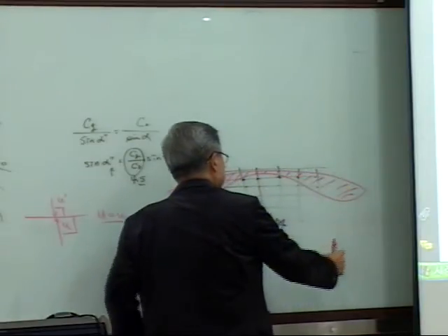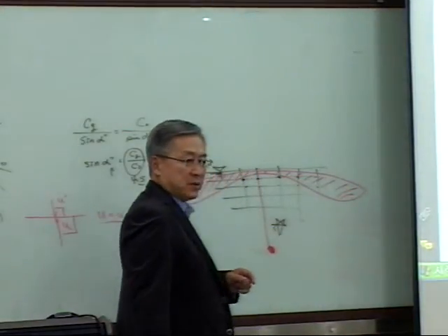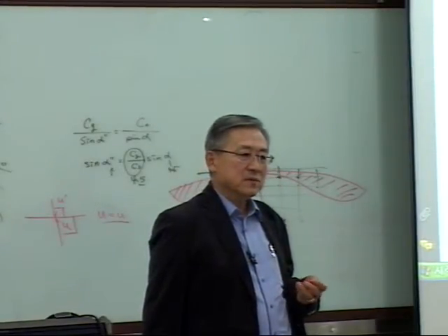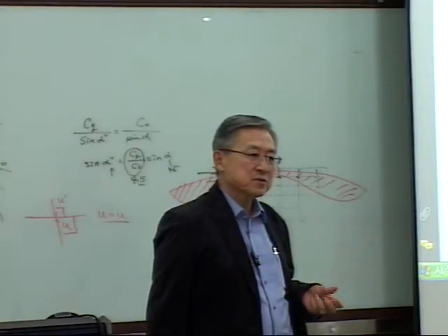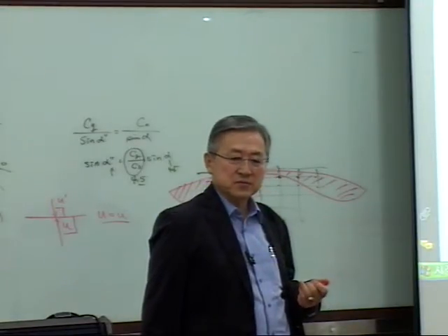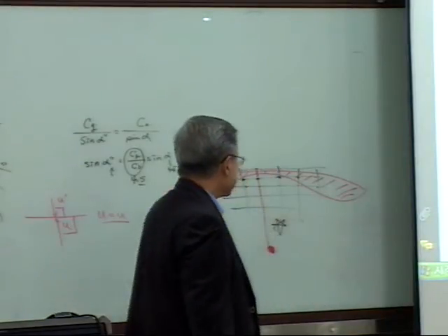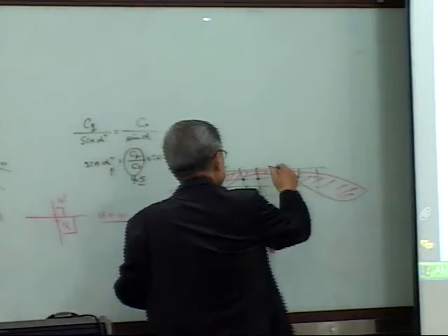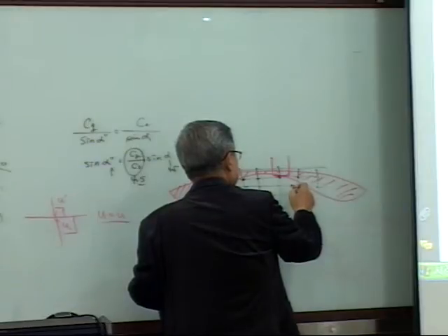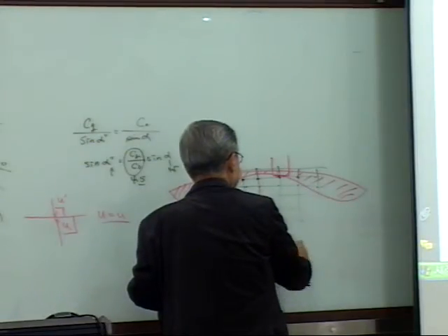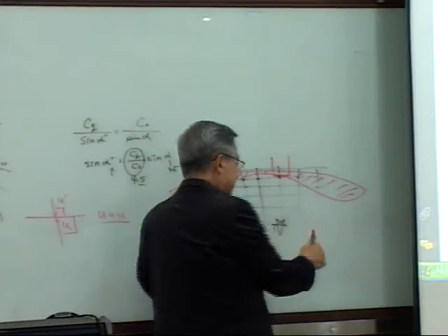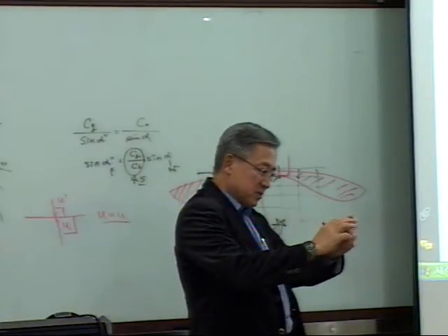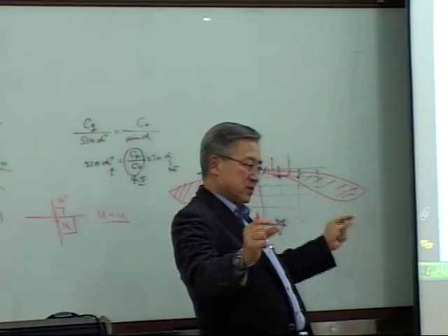It's almost flat. This range is big. When I say big, it could be 300 or 400 feet long for something like a 100-pound charge, which is 50 kilogram charge, vice versa. Then I'll show you how to compute all that. Bulk cavitation, very important. When ship is sitting here, then you have a multiple charge. Then, of course, bulk cavitation occurs the next moment.